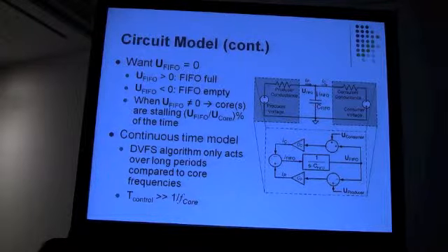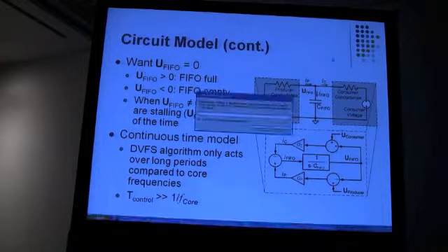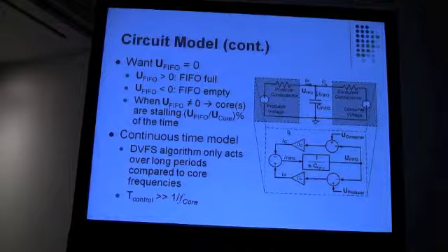I would clock gate, or could, that's basically what I would probably do. Power gate or clock gate this core, or power gate or clock gate that core, depending on this percentage number. So the percentage of time is what we want. But we want it to go to 0 because we don't want any of these to stall. We want to have the optimal energy point, right? Because I could always save power by just stalling these cores and power gating or clock gating, as the case may be.